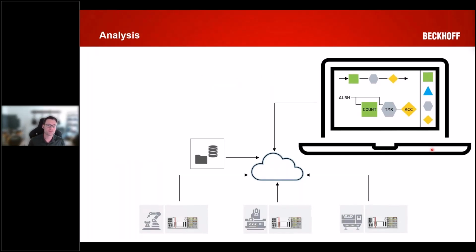Finally, before wrapping up analysis, we can take it just a couple steps further. Let's say we fall in love with this particular chain of blocks, our alarm analysis here, and we want to be able to apply it to all of our alarms instead of just one. Well, we could put on our programming hats and treat these like they're modules. We can pull out just the logic and parameterize the inputs so it becomes a reusable definition that can save time and reduce complexity and errors. It's just really powerful there to be able to basically generate templates.